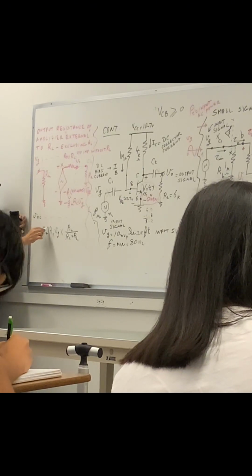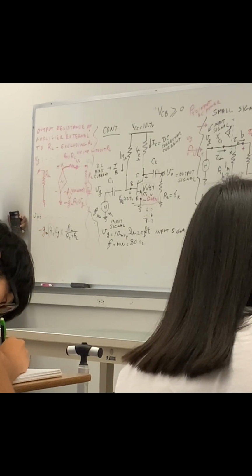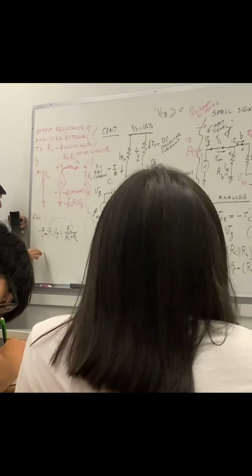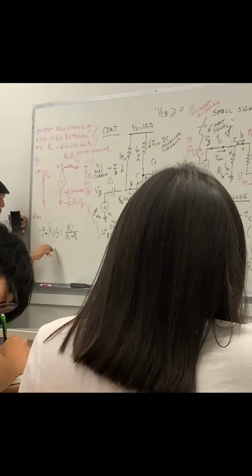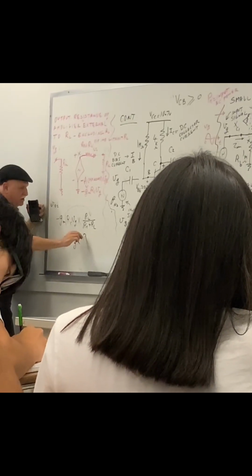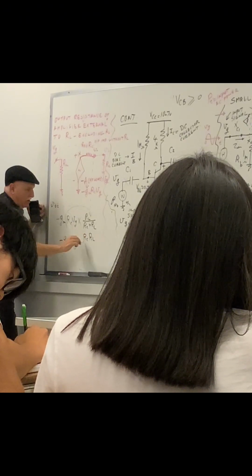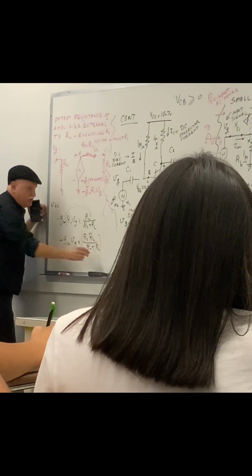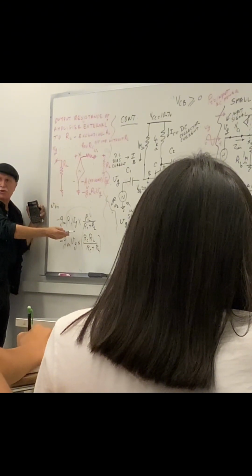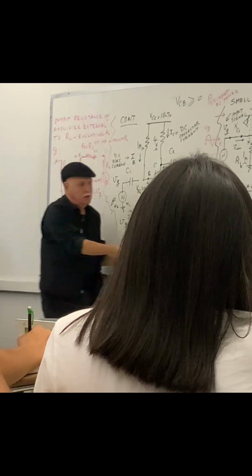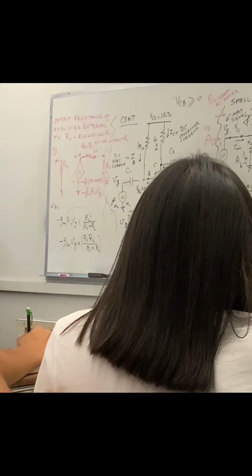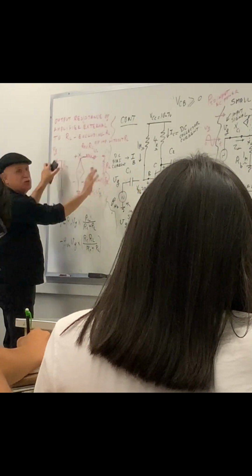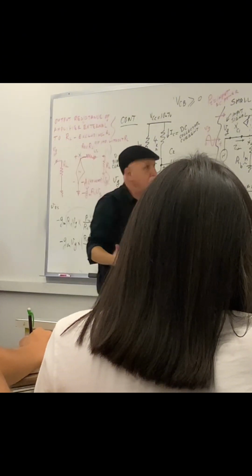Now, you see this RC, gentlemen, here? Move it here. You get minus GM VG multiplied by RC, RL, RC plus RL. Do you remember what this is? RC times RL over RC plus RL? This one. It came up to be exactly the same thing, except it's partitioned, apart from each other.